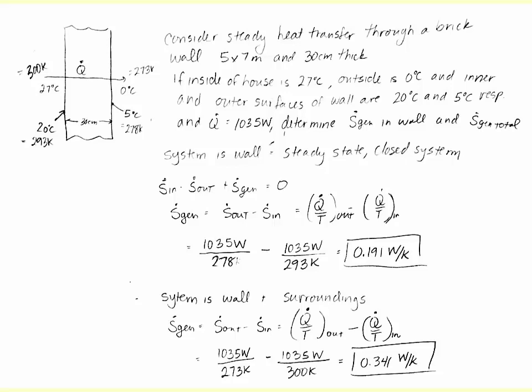So if we perform our energy balance, S dot in minus S dot out plus S dot gen is equal to dS/dt. Okay, because it's steady state, this term goes to 0. Do we have any mechanisms of entropy transfer into our system? So if this is our system boundary, is there any entropy being transferred into our system?